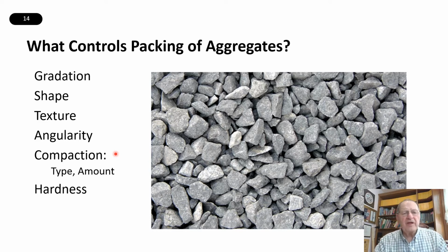Now, what about shape, texture, and angularity? Well, I have some flexibility here. For example, there is a fine aggregate angularity requirement, which is basically crushed faces on the fine aggregates. And I might have available to me natural sand and manufactured sand, and normally I might use a blend of those.